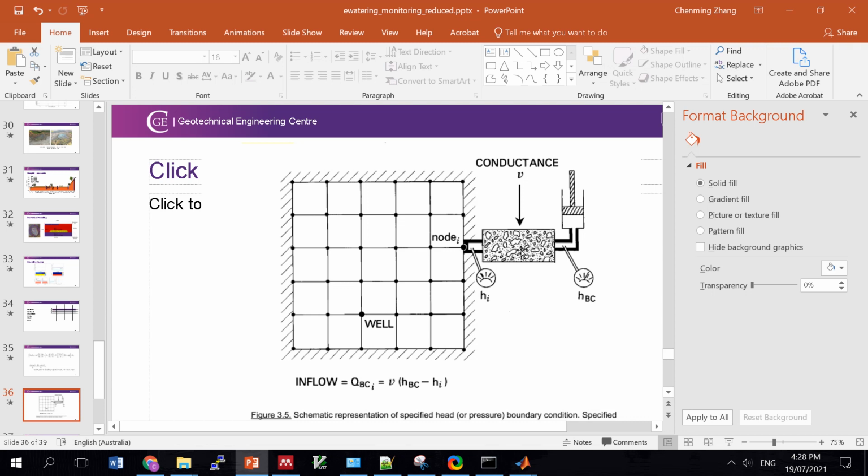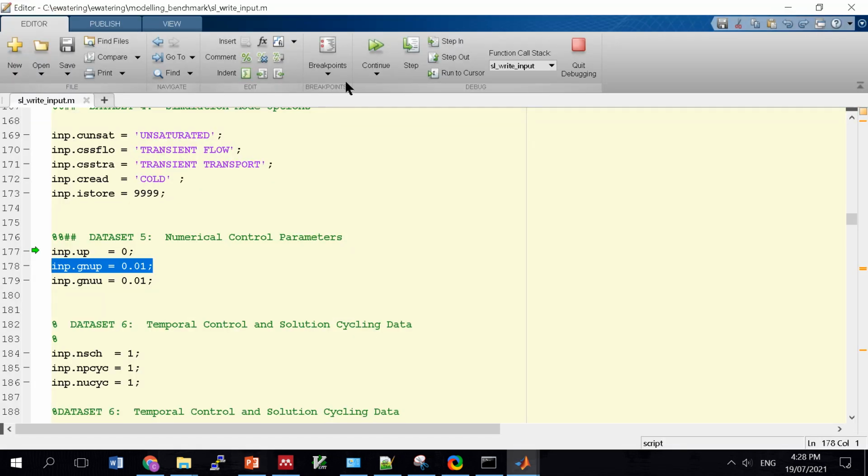But if your conductance is very small, you will see that the Mariotte bottle pressure is different from the pressure here, and then you're not really controlling the pressure here. So the good starting point is always 0.01, but the actual number needs to be very well justified. It's a bit of a numerical trick to get the right conductances, but the starting point is going to be 0.01.